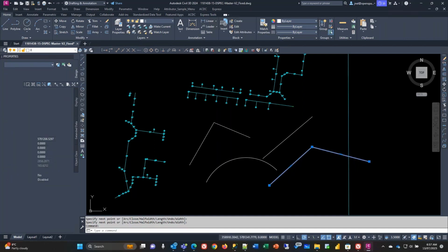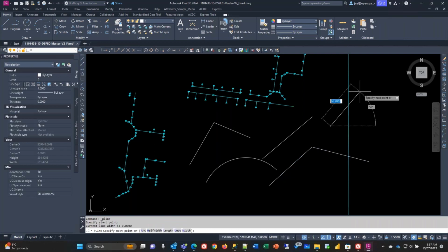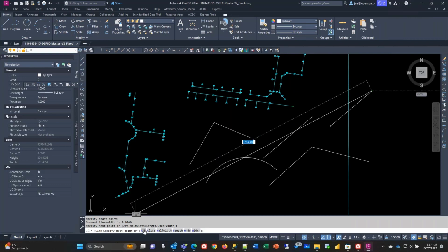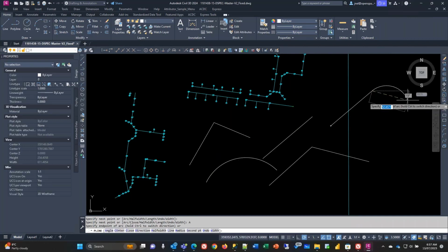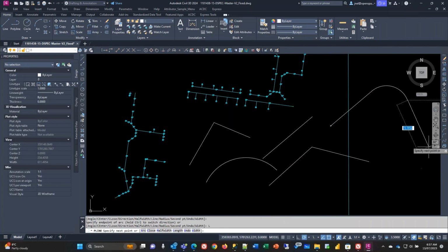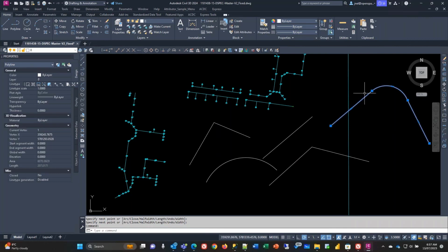If I say I want to draw a polyline, I can do a line, and then in the user interface say, all right, now I want to draw an arc in there, and to carry on, let's draw a line from that. Now you've got one entity consisting of lines and arcs in combination. You could also close that and create it as a closed polyline.